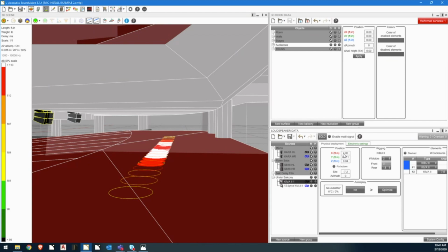So if I have, say, 8 groups of 2 boxes each of Kiva 2, I could fit all of those under balcony fills on one LA12X, which is pretty clean. I do the same thing with front fills and then X8s maybe. I will do, say, 6 or 8 X8s because that fits really cleanly on a single LA4X or an LA2XI. So I like to do even pairs. So we're going to start with 2. We're going to move them around off center until we get a good distribution of the 2.